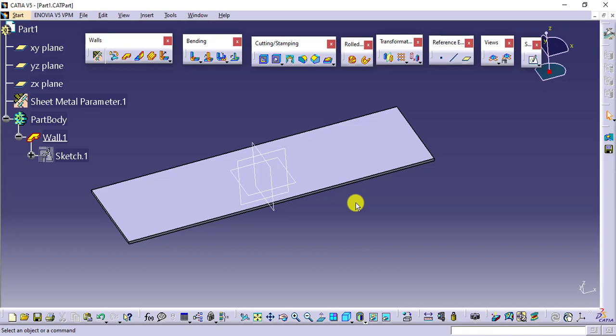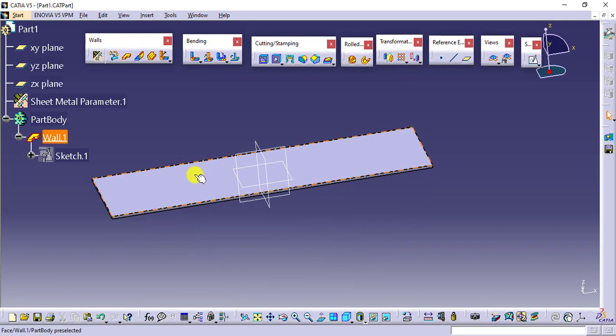Remember, we are using the first approach in the sheet metal environment, which is by adding the walls. So to this primary wall, I'll be adding another wall, and like this I'll keep on adding the walls to get the final result. Practically, adding the wall is not possible when you talk about the production of sheet metal entities. But for modeling, yes, we do have this particular approach available which we can follow and get our desired result in an easier manner.